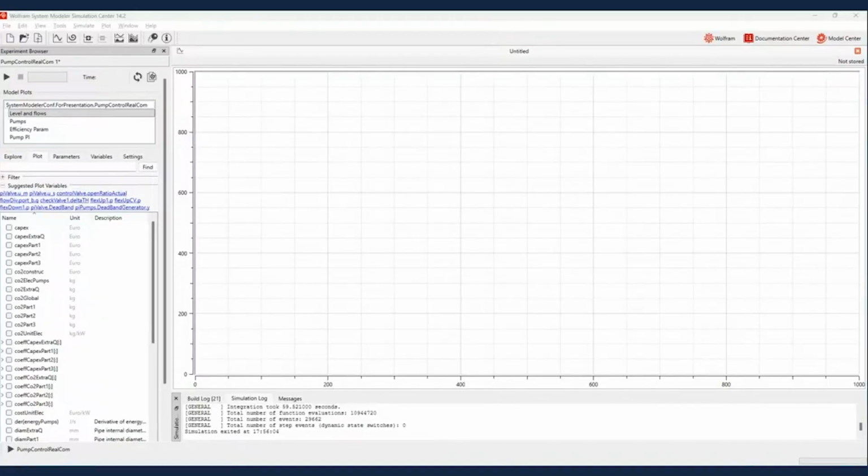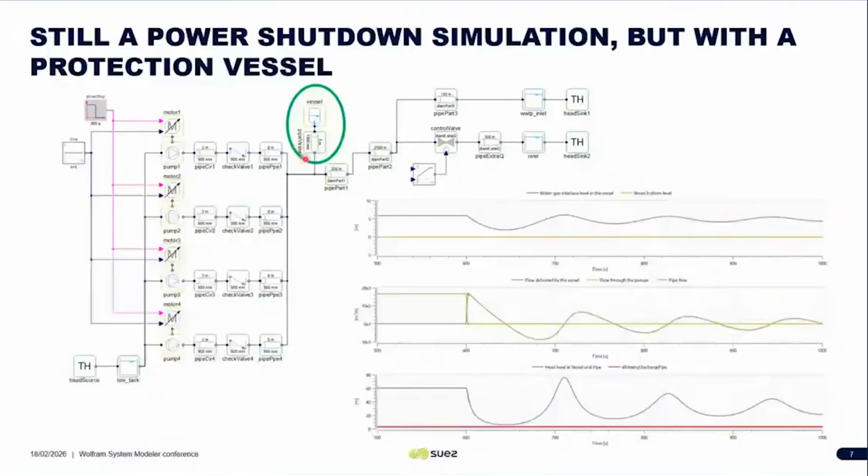So in this sense, it's to approach the vessel to the pumps, which are the element that changes condition upon power failure. If we place it further away, the phenomena will develop until they find the vessel, and so we end up with two oscillation systems, one upstream of the vessel and another one downstream. I don't know if this was the question.